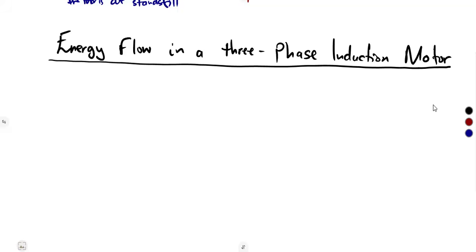As we have the stator, in the stator there are losses. In the rotor, there are losses. There are also losses in part of the bearings. All these losses, guys, they represent part of what? Power. So it's power being lost. So which losses exactly are we going to consider in our energy flow? So remember, we've got part of the variable losses, which is your copper losses.